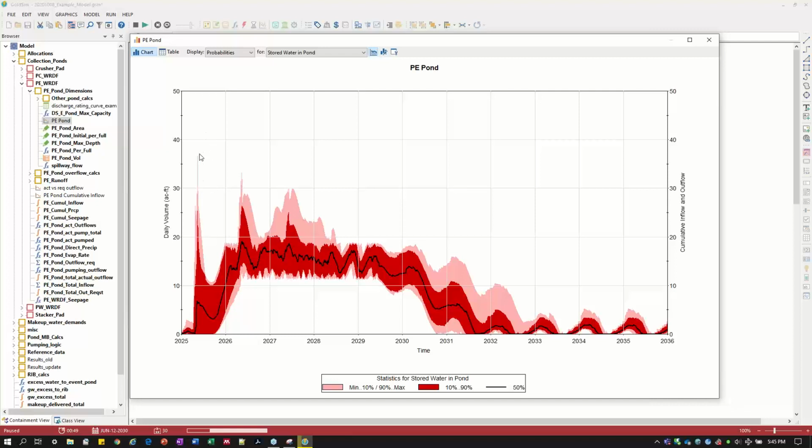So there's potential, when you build this pond, depending on the contributing area, or if you have any kind of upstream controls, you can potentially get runoff events in those first couple of years. But as that footprint expands, you kind of get into these interesting trade-offs between how much of this reclaimed area is going to report to the pond versus how much of the seepage that's coming through the bottom gets there. So there's a lot of dynamic things that are happening at the same time, and the details of that, that's why mining is interesting. There's always more details to this type of work.